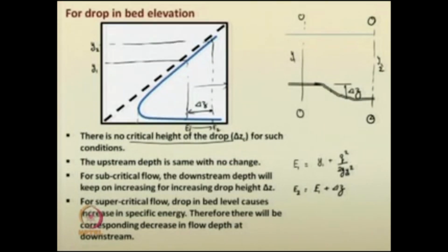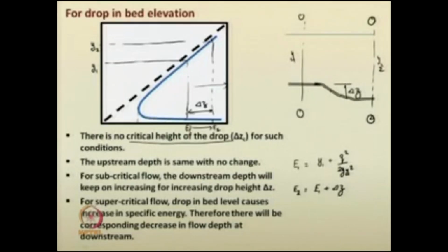The energy is only increasing if you increase the height of the drop. So, that way there are no such critical conditions arising here. You will also see that the upstream depth will remain the same, with no particular change in the flow profiles. For subcritical flow, the downstream depth will keep on increasing as you increase the drop height.